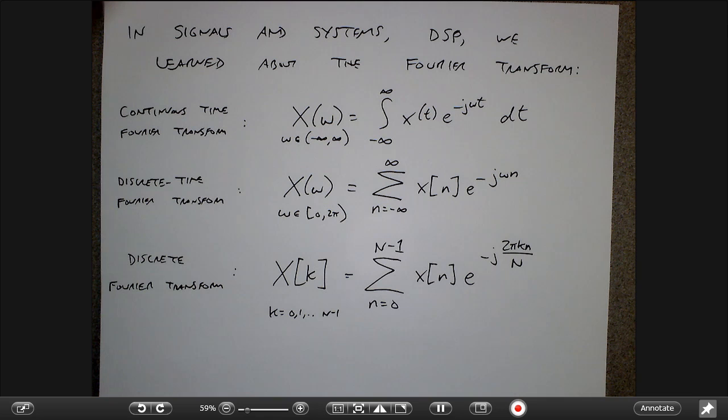We talked, for example, about how you could use low-pass filters to remove static-y sounding noise from a signal. We talked about how multiplication in the frequency domain corresponds to convolution in the time domain. That's why it was so easy to apply linear systems in the frequency domain, because all we had to do was take the Fourier transform of both the filter and the input, multiply them together, and take the inverse Fourier transform. All that holds together for image processing as well, right?